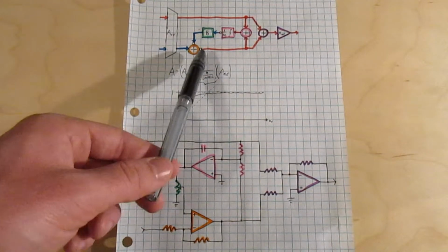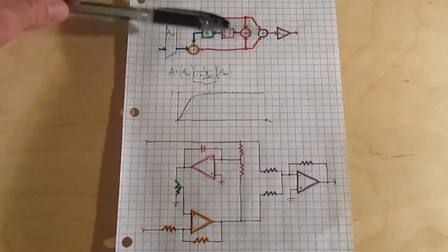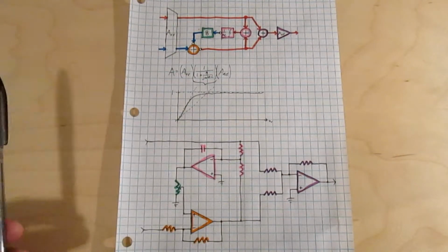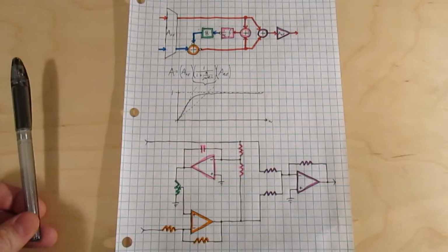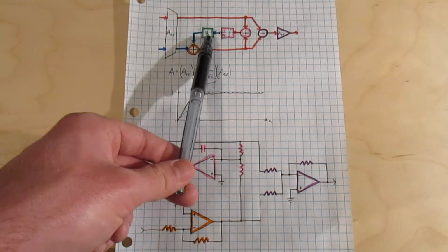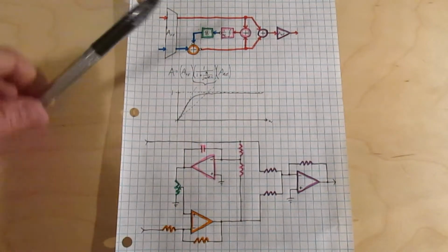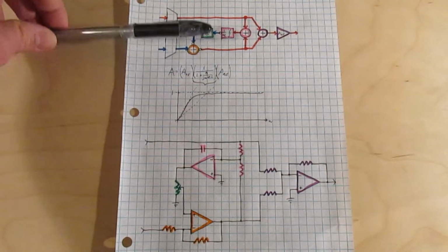And after I came up with this, though, I noticed a problem with it. And that's that the integrator has a limited voltage range. There's some maximum voltage and minimum voltage that it can give at the output. And without the attenuator, that would be the maximum and minimum amount of DC offset that I could track out. But with the attenuator there, I can only track out half that much. And that means that the range of DC offset that I can actually cancel out is only half what I otherwise would be able to do.